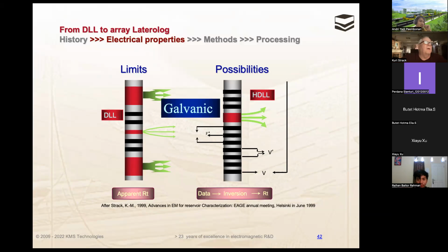So then a new way, which includes geophysics, is you simply inject the current and you let it flow wherever it goes. And you measure the voltages on a multitude of electrodes. You measure the voltage with respect to a surface return. You measure the voltage between electrodes, and you measure the second difference or the derivative of the voltage between 3 electrodes.